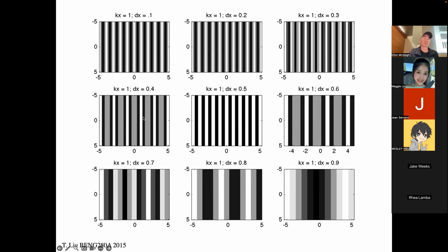And so now my representation of the frequency doesn't look great. This is 0.5, and I have 1 up, 1 down, 1 up, 1 down, 1 up, 1 down. And so this is the lowest sampling frequency I can use in order to reconstruct this sine wave well. Once we get to 0.6, this is what it looks like, 0.7, 0.8, and then 0.9, we start to see this really low frequency stuff folding back in.